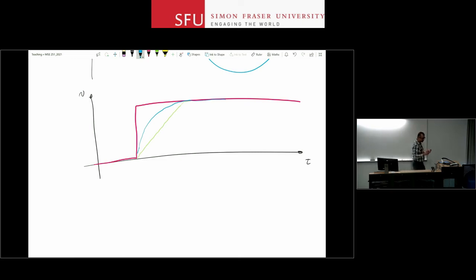And the funny thing is that this looks like a ramp. In most cases, it's just a straight line, a true ramp from the input all the way to very close to the final value, and then maybe it follows the exponential curve. So what's going on here? This slope, dV out over dt, once you hit this limitation, once you hit that ramp-like behavior, it's more or less constant.